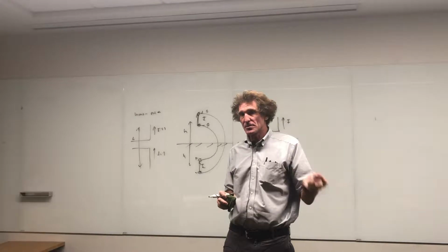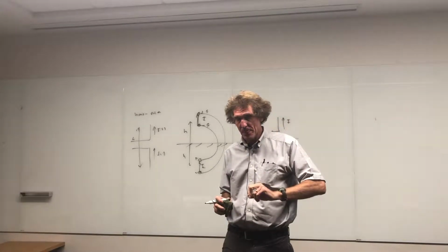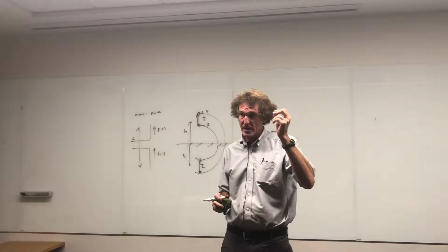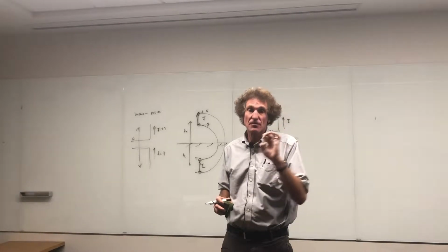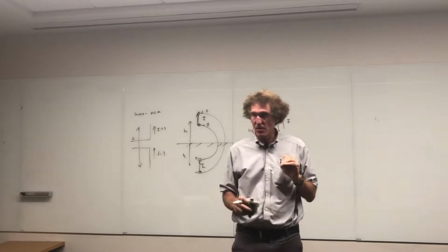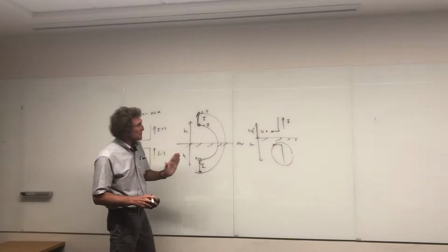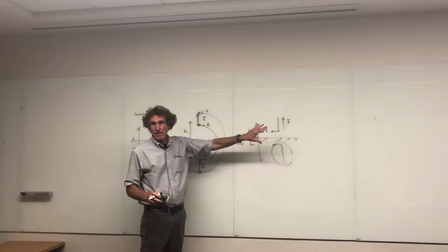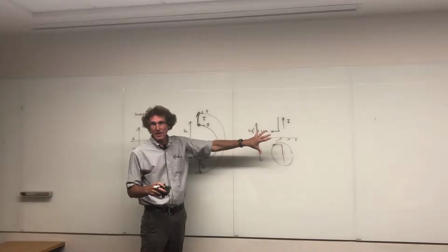The power is proportional to the radiation resistance. The radiation resistance goes down by a factor of 2, but the gain goes up by a factor of 2 as well. Radiation resistance down, gain up. Does that make sense to everybody? For the same current, that's what I'm getting at, for the same current that's flowing in that thing. Now, that's for currents flowing in the same direction, and this is the monopole. We could go through the gain and stuff like this, but it's not important right now.